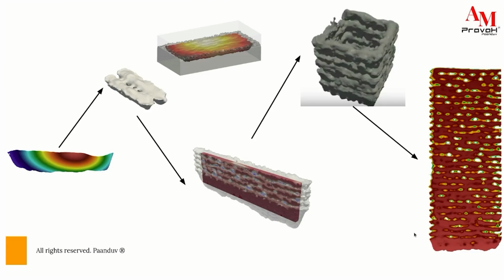Now, when you do CFD simulations, you get the information about velocities, about pressures, about temperature. In-depth understanding of temperature evolution in the entire part will help you understand, if you leave a thermocouple at any point in your system, how the temperature will be evolving. So you can get the information about thermal cycling plots at any point in the system. And these thermal cycling plots can also reveal the information about the cooling rates and the temperature gradients in the system.